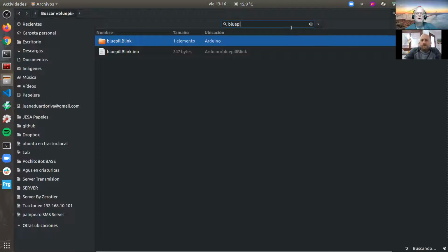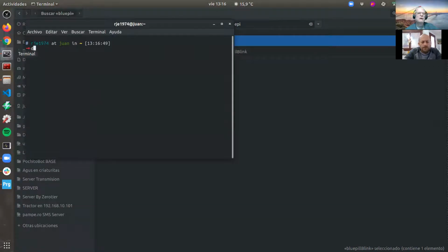No. Because right now you probably don't have any code on that board. If you plug the board in with USB, did your computer say it recognized it, or does it not do anything? Yes, it recognized it, but I'm not sure where it's showing me. No, it does the sound, but are you on Linux or on Windows? In Linux. So go to your command line, do a dmesg, DMESG, and that should show you on there.